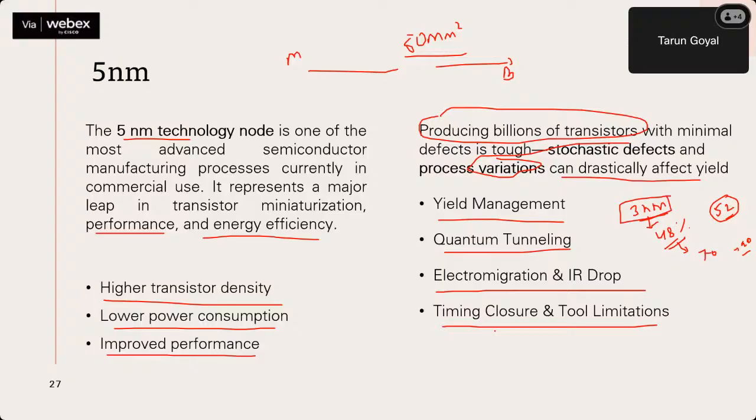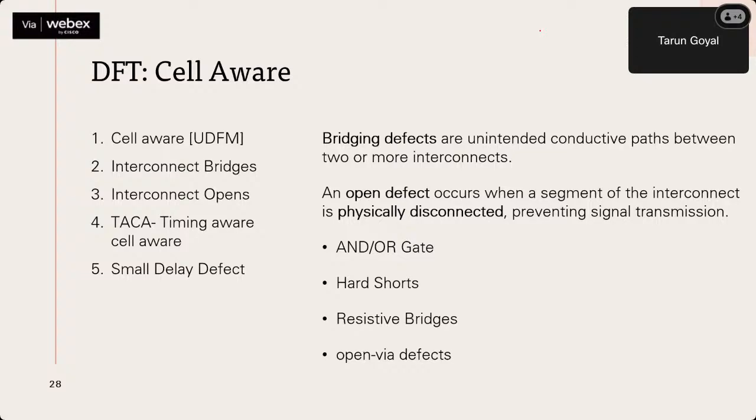Okay, so how does it impact and how does it come to DFT? When we went to millions of transistors, we were testing here. Now we are testing billions of transistors. Here metal layers were like this, now metal layers are like this. More dense metal layers, more defect prone, more aggressor-victim bridges and all. These things start playing. And nowadays, if you talk about the new term many of you may have heard, silent data corruption, all these things are happening, and all this has to be detected.